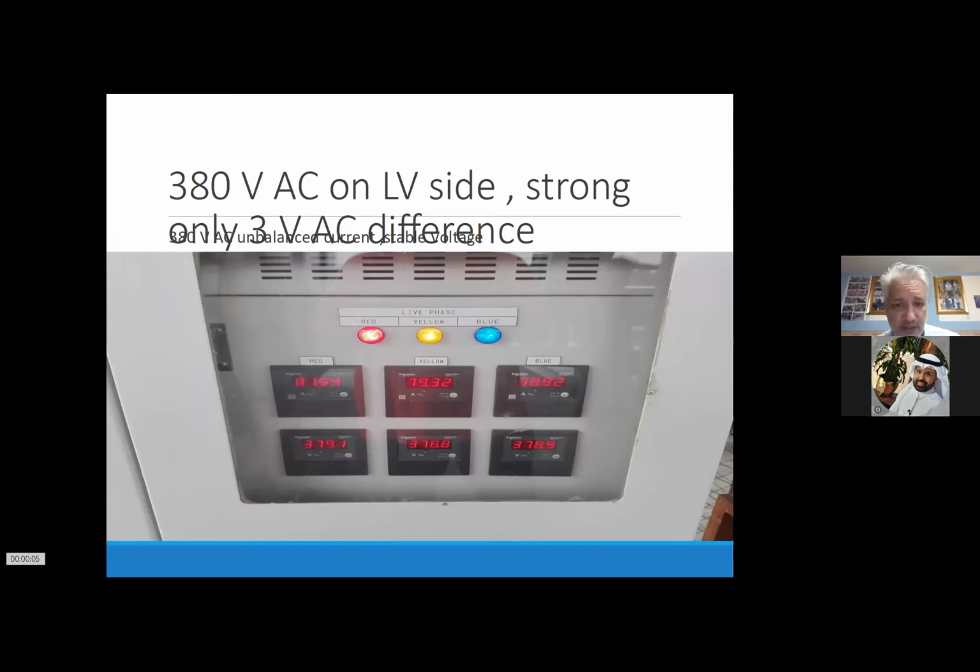You can see the 3 different phases and how much power they can actually inject. Here, almost 80 amps, and the voltage is 380. So it could be that it is a soft voltage, so that means it actually dips down. So it means it goes towards 360 sometimes. Then you change the transformer to 400 volt and you check again.